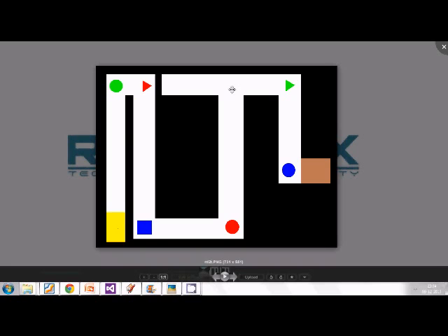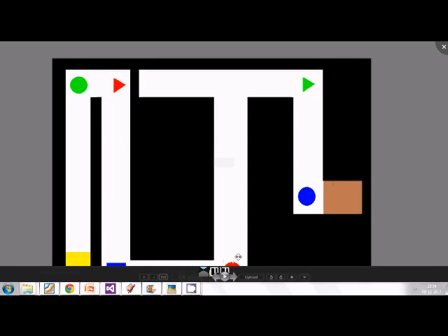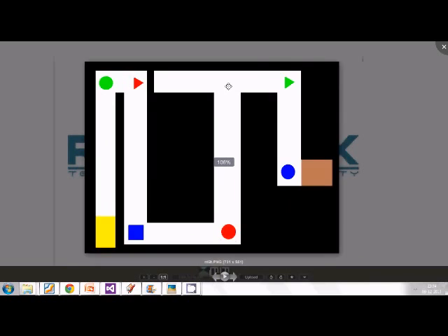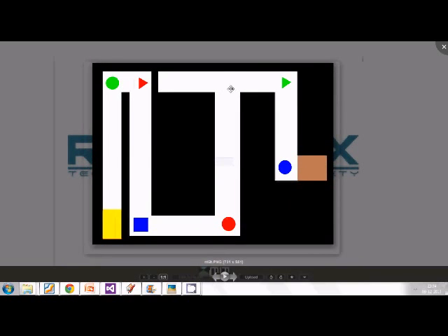You can use something called CV line iterator, where you join the two points. It will iterate over all of the pixels along a line, and if there are no black pixels or very few black pixels, then you know that this is accessible from one waypoint to another, because you can directly go through white area, all of which is accessible. So that is one way we'll create waypoints of our own in front of the T junctions instead of just using the symbols.